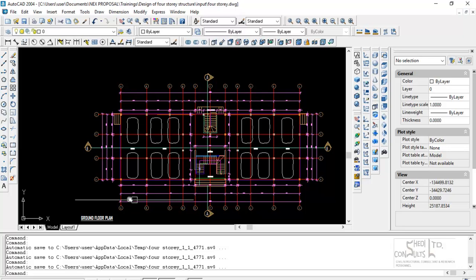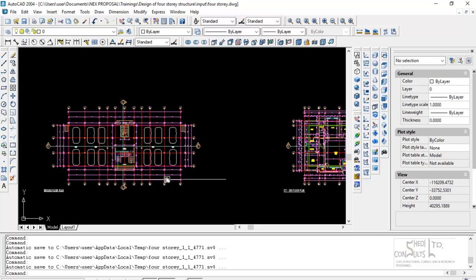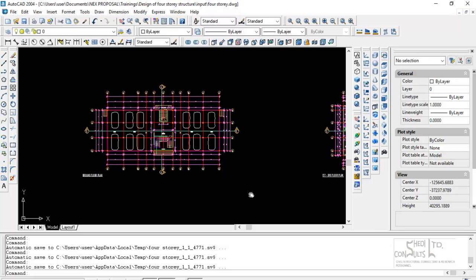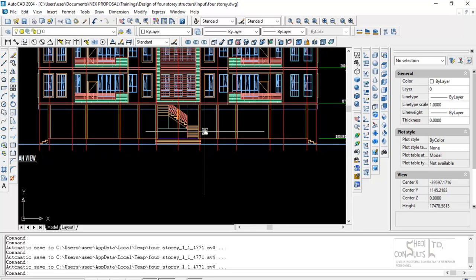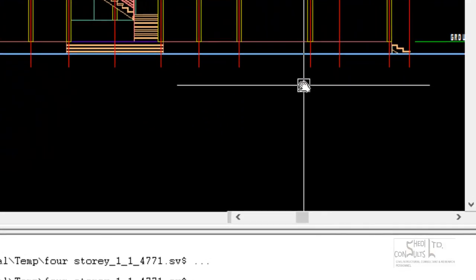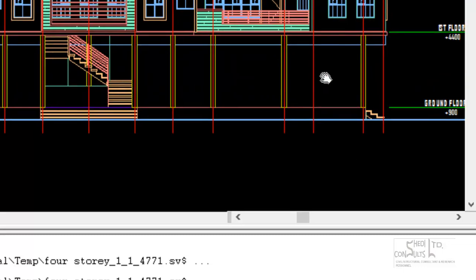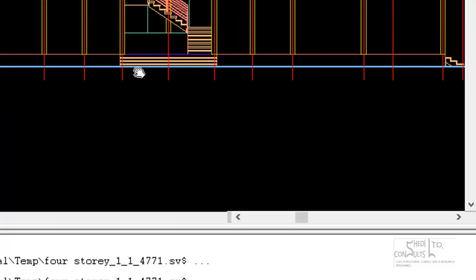The site was originally a dump site and was filled with dump materials. Particle sizes less than 0.002, indicative of organic clay, were present on site, up to 20 meters. The site was so poor, and this is the reason why the architect decided, in compliance with us, the structural engineers, to elevate the entire structure so that it will be sitting on a very deep pile foundation.